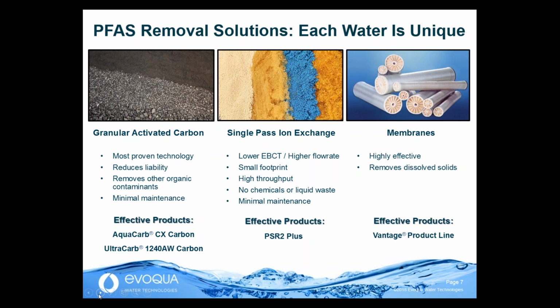Moving into single pass ion exchange, this technology has been validated in the field, and we have some great data to show later in the presentation. This requires a lower empty bed contact time, which translates to a small footprint. So if footprint is an issue, this is a technology to look at. And we have seen high throughput. It is also important to keep in mind that with single pass ion exchange, once it is spent, it will need to be either landfilled or incinerated.